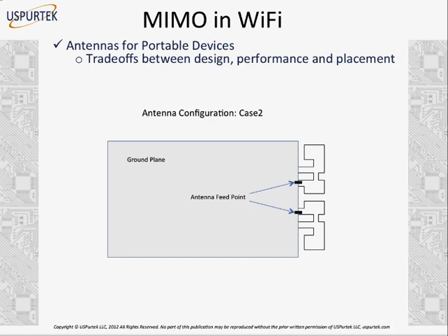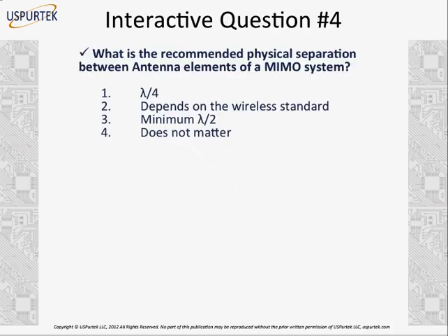So although you sacrifice diversity a little in this case because the antennas are closer now, you gain advantage in other ways. Your feed points are closer, so your losses due to feed points being far apart are reduced now, right? So again, it's up to the actual device, how you physically implement this design inside the device and which one is best for any particular device. But again, trade-offs are there. You have to trade off one thing with the other.